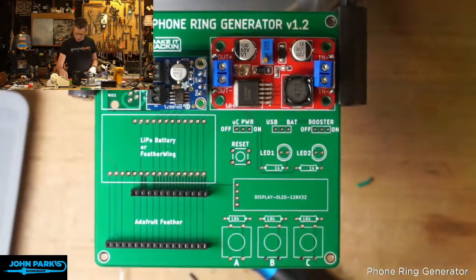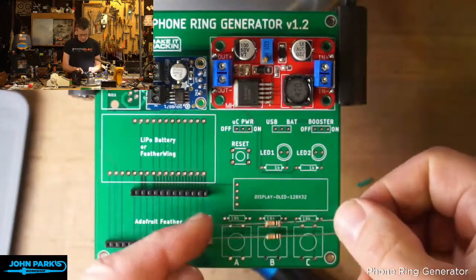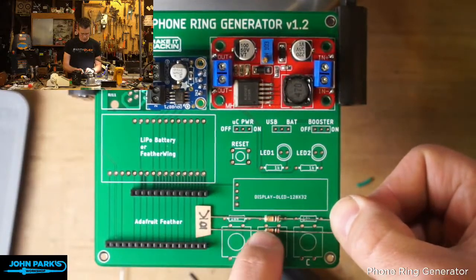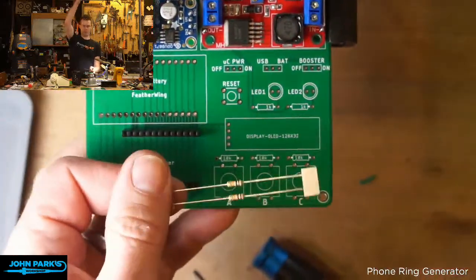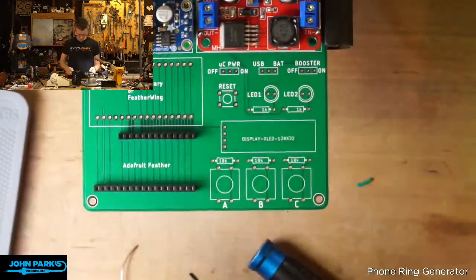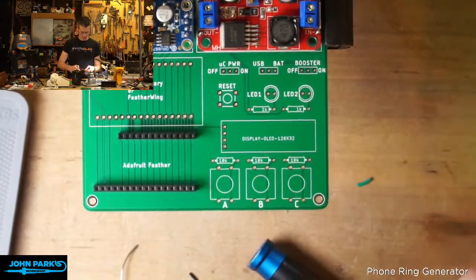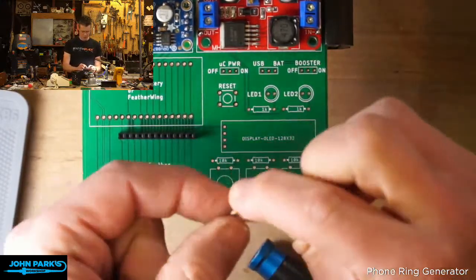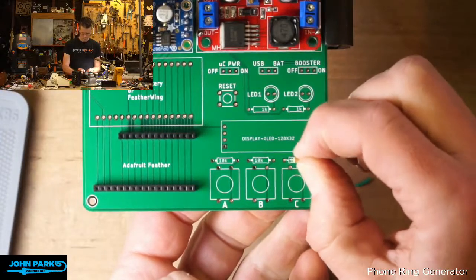So these are 10K resistors for the buttons, in case your microcontroller doesn't support that. The spacing on these is basically as tight as you can bend them, which is one of my favorite choices by footprint designers, because it makes it easy to just bend your resistor legs by hand. So these are 10Ks. I verified that with a multimeter earlier, just because it's sadness when you have to replace resistors because you put the wrong values in, or any part for that matter. So these will go in like this.